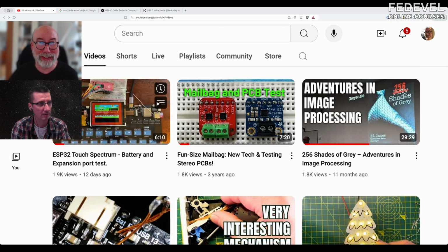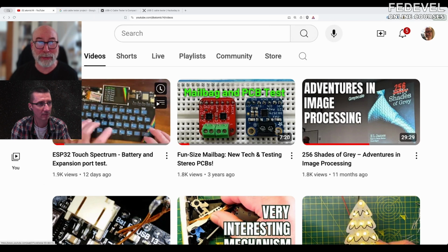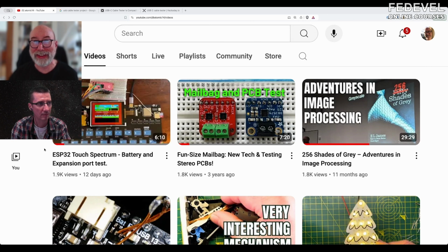And that's why on this version there's 5 more ICs along the top here, which are analog multiplexers. So I ended up multiplexing the analog touch signal out to each individual key. So every single key is now its own touchpad and gets multiplexed back to the ESP32. I'm still amazed it actually worked. I can't quite believe it worked. I built it on some breadboard to test, and it worked. And I was sort of, this really shouldn't be working.